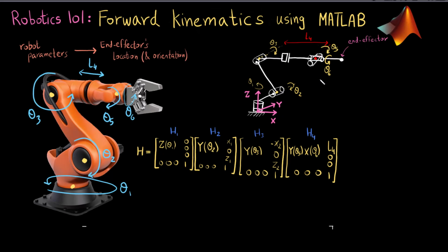And why have I done it first in y and then in x? It is because of how the robot is constructed. We can see here that first it is going to be rotating about theta 5 if I go from the base towards the end effector. So first there is a rotation about the y-axis, and then there is a rotation about the x-axis.